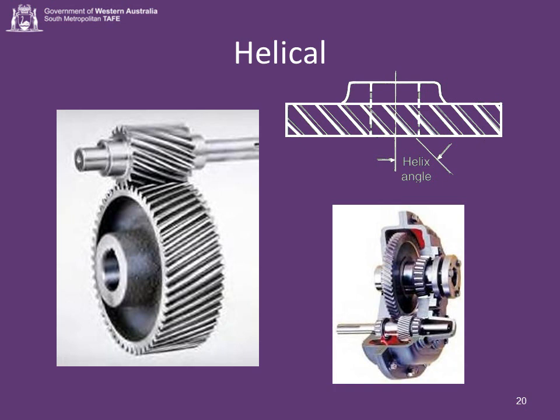The shafts are in the same plane and parallel, but the teeth are cut at an angle to the center line of the shafts. Helical teeth have an increased length of contact, run more quietly, and have a greater strength and capacity than spur gears. Normally, the angle created by a line through the center of the tooth and the line parallel to the shaft axis is 45 degrees. However, other angles may be found in machinery. Helical gears also have a preload by design. The critical force to be considered, however, is the thrust load, axial load, generated in normal operation.